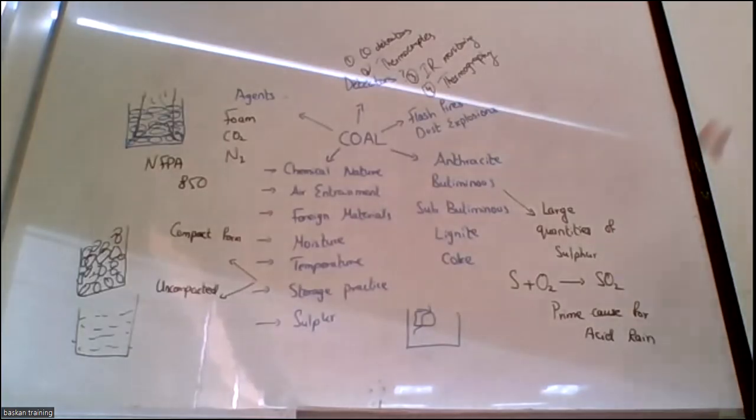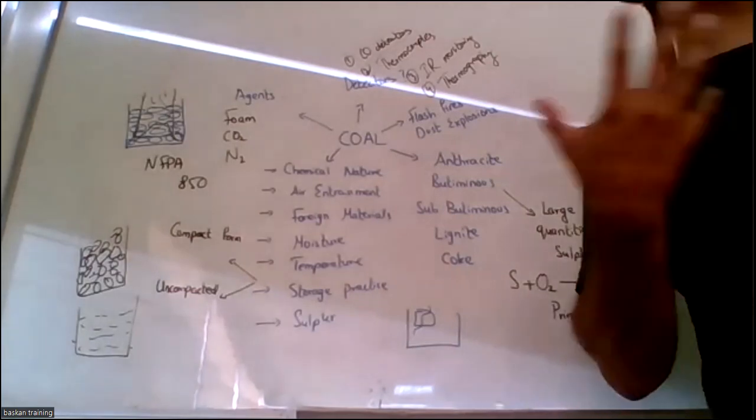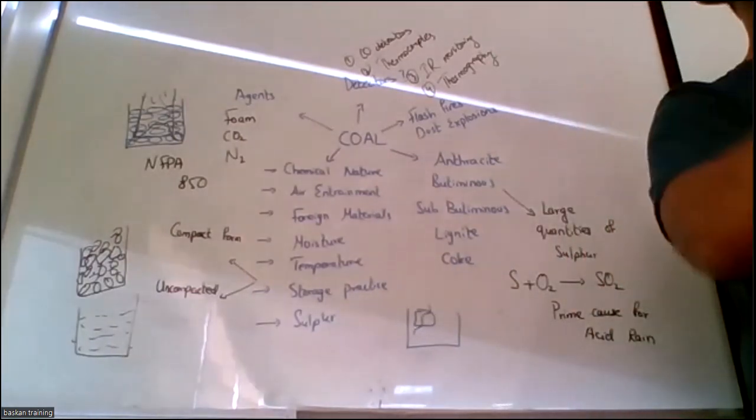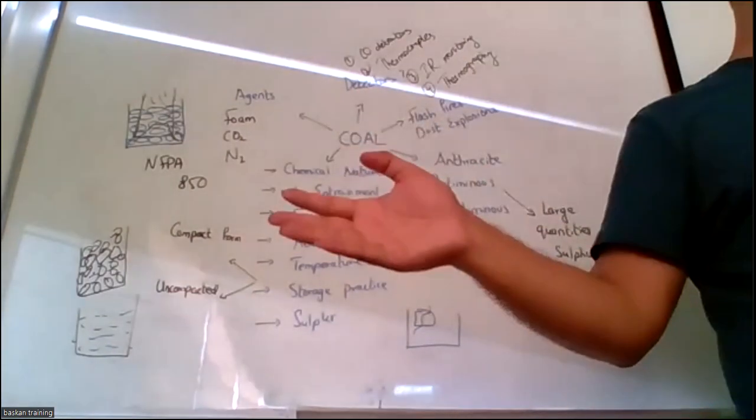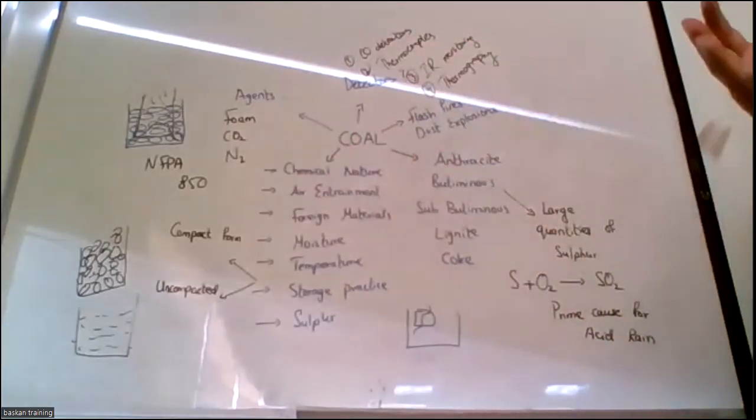Appropriate ventilation is required, okay? And you cannot store coal for an extended period of time. You have to utilize it. That is why, whenever coal is stored for an extended period, it can go from moderate combustion to flaming combustion. A very high combustion stage can occur at any time.